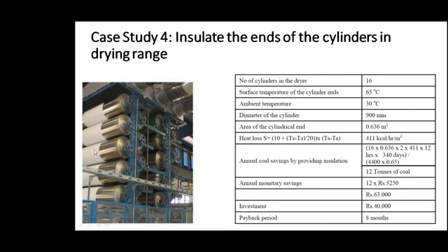But if you see this portion, the cloth occupies only maybe about 30% of the cylinder width. The remaining portion is empty. So a very simple suggestion is to hold this cloth for some more time till one more batch comes. So you put one more layer of cloth here, one more batch of cloth, so that it can cover the entire section.